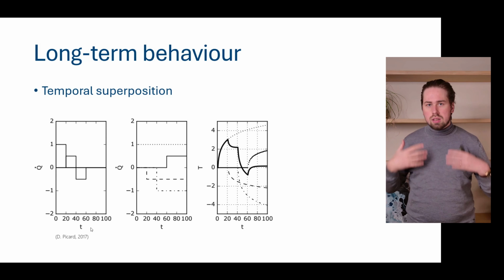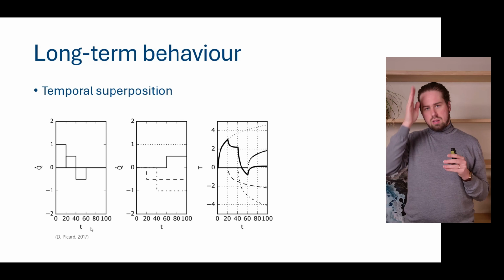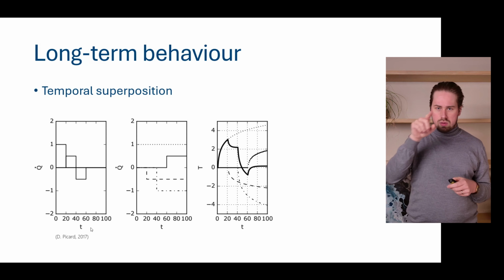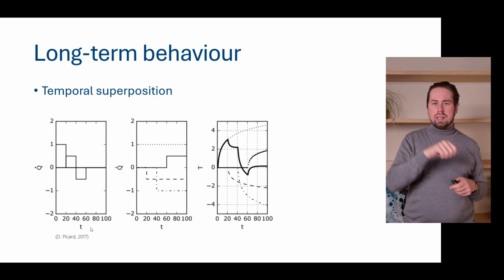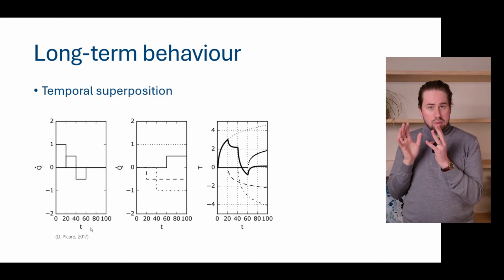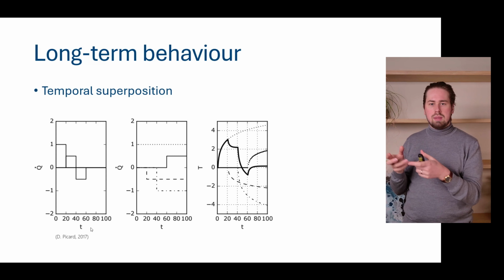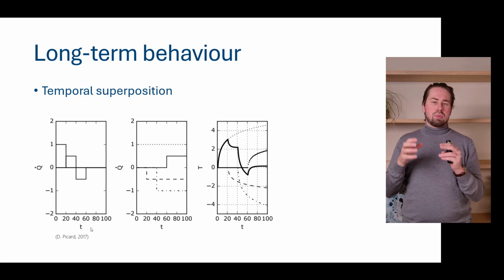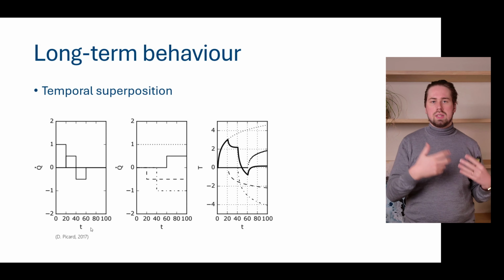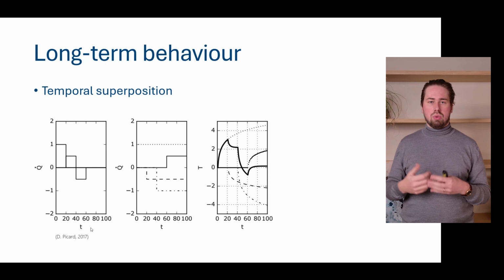And our resulting profile is now just the sum of, again, all these G functions at all these different steps. And that's the bold line you can see on this graph. By doing so, we can use this simple concept of our ground response functions, the G functions, how we can influence them, and basically use this temporal superposition of all the different loads at all the different times to end up with a resulting seasonal and yearly variation of our wall temperature.